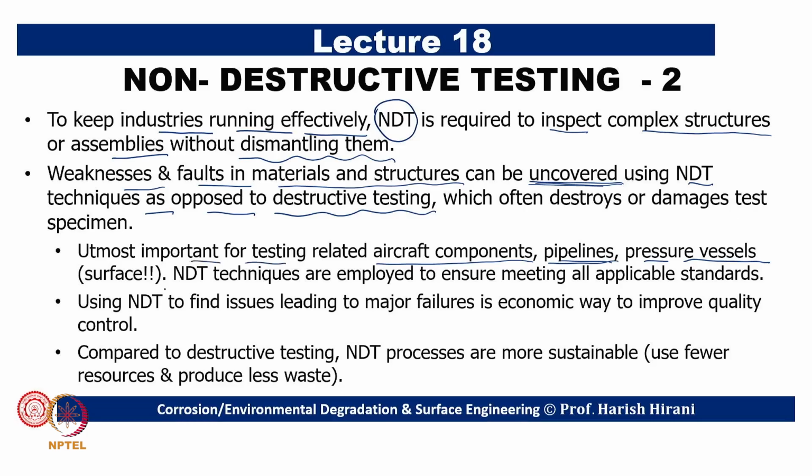Of course, we are writing here because we have been giving most of the emphasis to surface failure. We are not giving much importance to complete fracture. In this case, if something is wrong on the inside surface of a pipeline, I will not be able to understand it from outside. So, those failures are also required to be detected, whether the thickness of the component is continuously reducing because of corrosion, and when the failure will occur. That is why we are including this feature also.